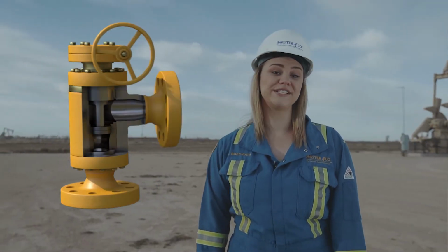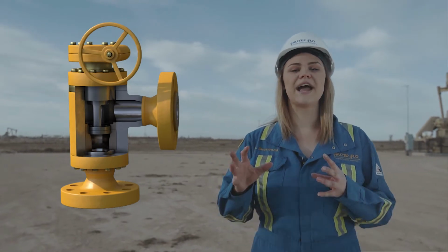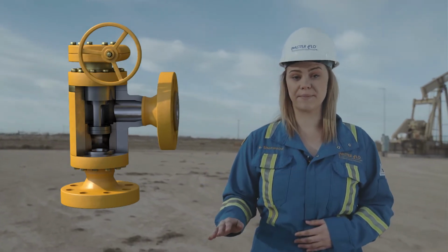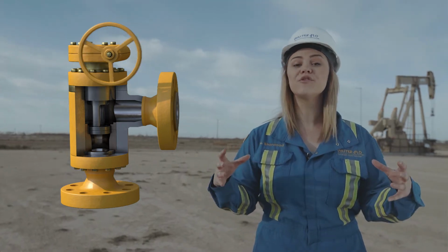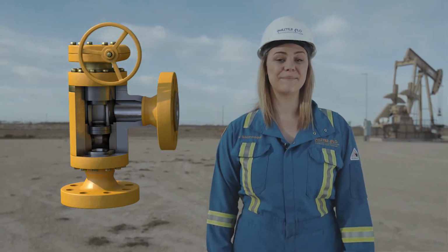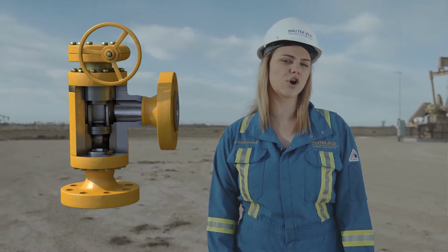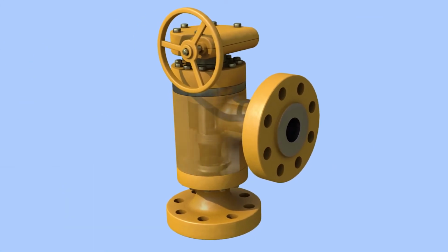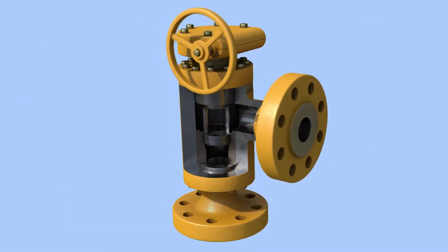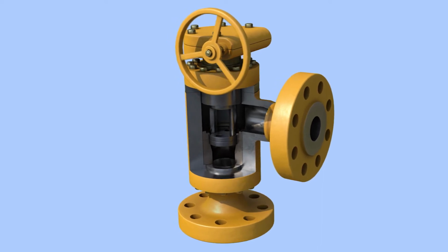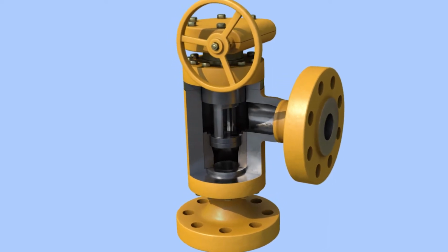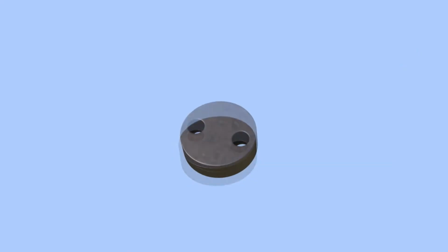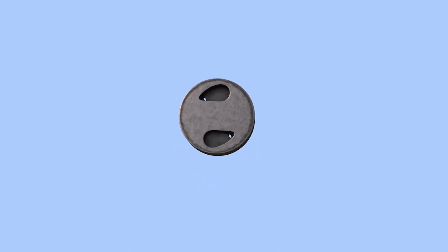Multiple orifice valves, or disc-style choke valves, provide improved flow control and shutoff capability. When these openings are perfectly aligned, the flow rate is maximum. When these openings are offset by 90 degrees, it shuts down the flow completely. Erosion is common around the edges of the holes. The high-velocity jets from the throttling ports flow into the valve outlet, resulting in high potential of valve body erosion. As the discs wear out, the valve's shutoff function could be lost.